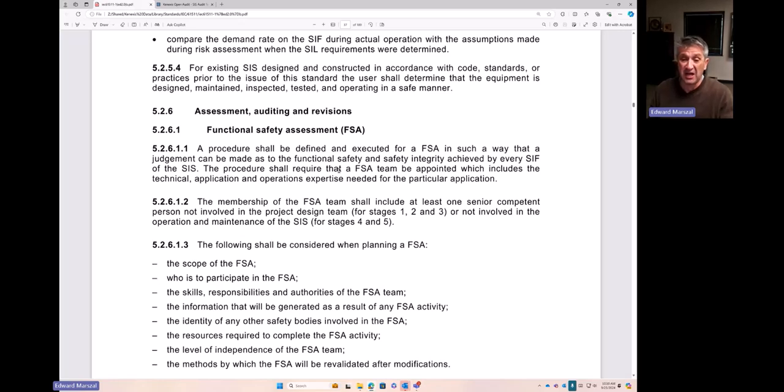Was it done the way that we said we were going to do it? So auditing is kind of a big picture item. It's discussed in a lot of detail in the OSHA Process Safety Management Rule, or whatever legal framework applies to the country you're in is probably going to be very similar, whether it's COMAH or SEVESO or what have you. They all have very similar requirements to each other.